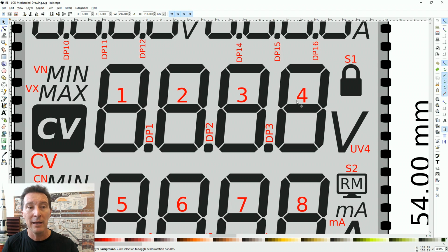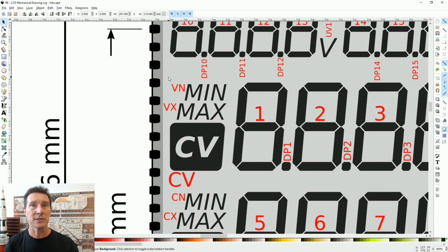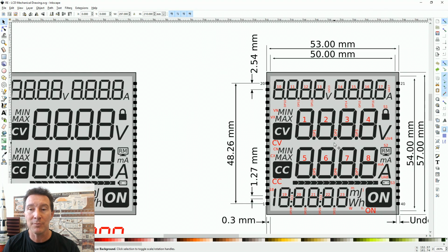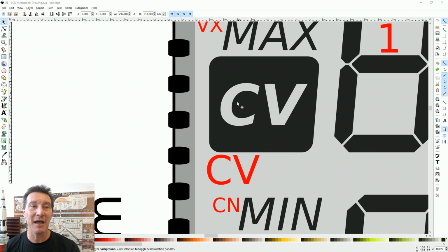So you can see why, if you wanted this segment here connected over to here, we can't do it. They're just going to absolutely scream at that sort of thing. And basically they might say they can't do it, or they might have a process to do it. But just be aware, routing is a big issue with something like this. And of course, you can't just manufacture something like solid segments, for example. You have to have the gap between the particular segments.